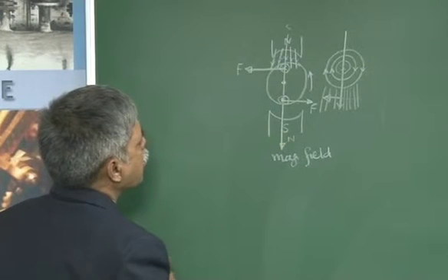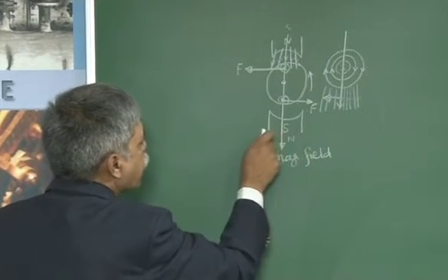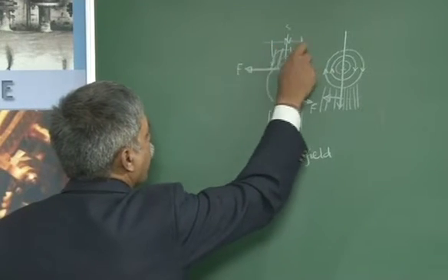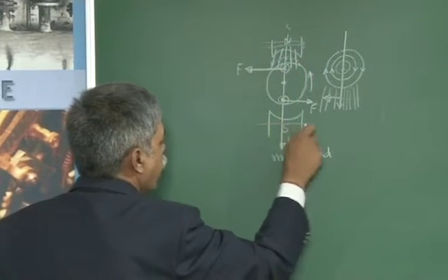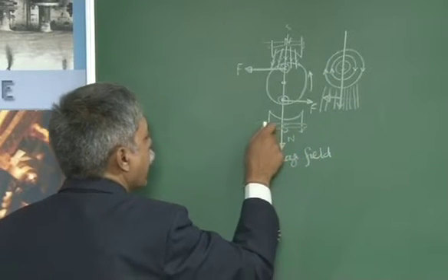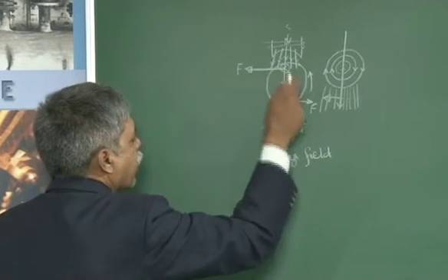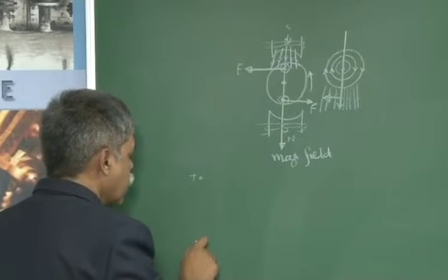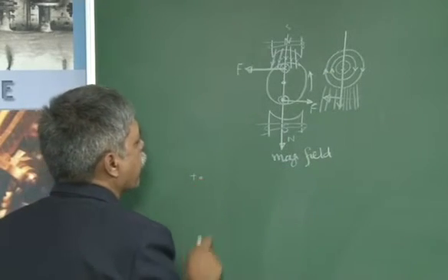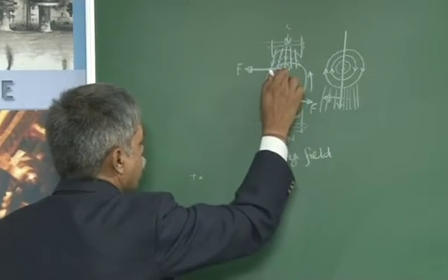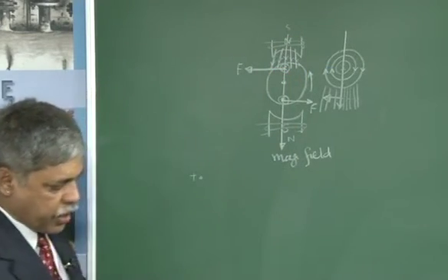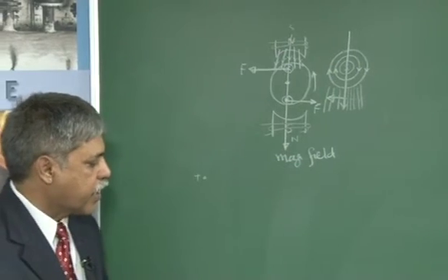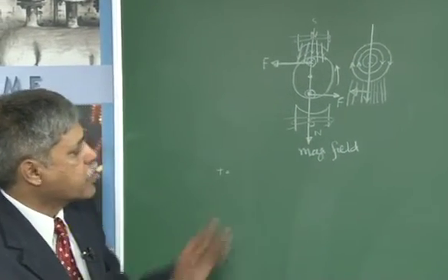In the case of a shunt motor, if the magnetic poles are produced by a current, then I will be having a winding here. The winding on the poles and the winding on the armature are connected in parallel to a DC supply. So, this DC supply is responsible for current in the field winding as well as the current in the armature conductor. I need to send current through the conductors so that these current carrying conductors experience a force.